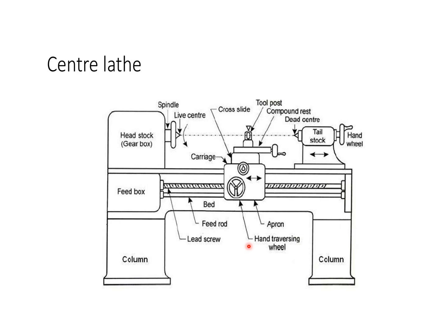Next, lead screw. The lead screw is a long threaded shaft used as a master screw and brought into operation only when threads have to be cut. At all other times, the lead screw is disengaged from the gearbox and remains stationary. The rotation of the lead screw is used to traverse the tool along the work to produce screw threads. The half nut makes the carriage engage or disengage the lead screw.